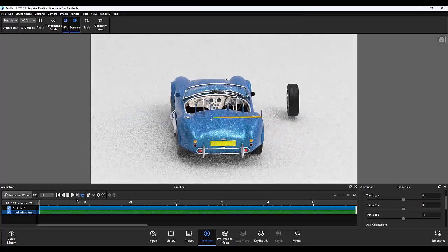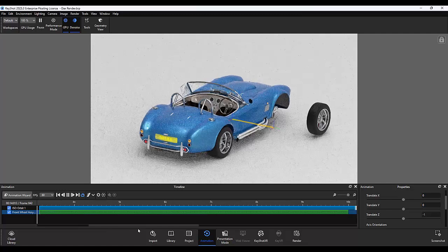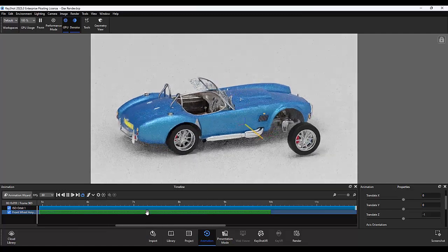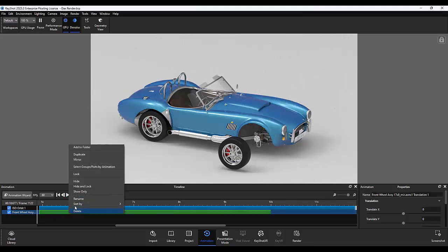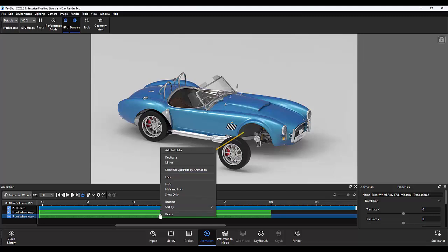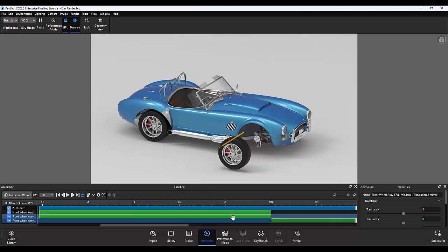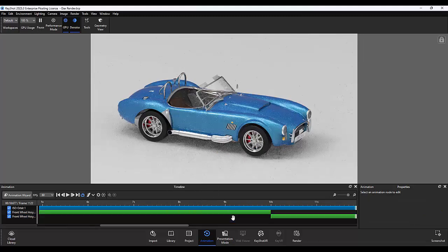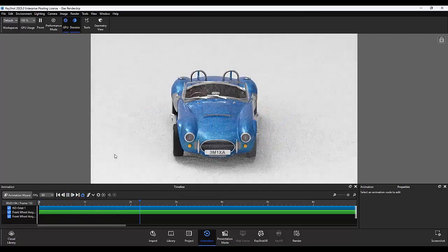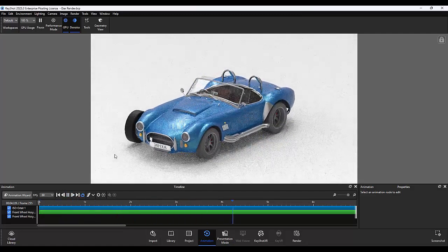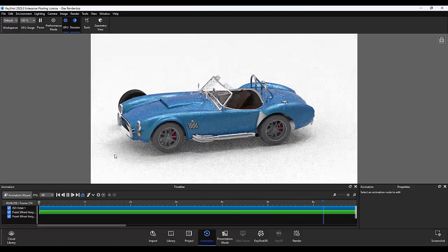So you can see that when I've added in that model animation, the wheel has now come away from the rest of the model. And instead of having to recreate an entirely new animation, what we can do is go ahead and duplicate and mirror the existing animation. And this will essentially duplicate the animation but in reverse, because we've created a mirror image of that animation itself.